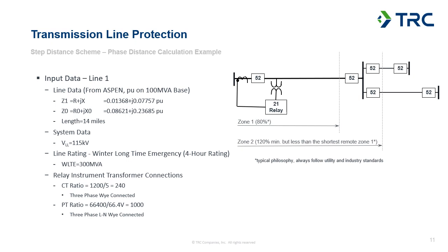And we're also going to need to know about loadability of the line because we're going to be stepping primary measurements of primary currents and voltages down to secondary quantities. We're going to need to know some information about our instrument transformers, so current transformer ratios, potential transformer ratios. And we'll use all that information to go through a series of calculations and determine the appropriate settings we'd load into the relay to have it operate for the application in the way we want.